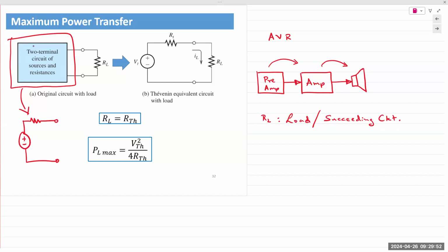Again, taking that example one step further, if you look at the speaker specs for any speaker, tiny drivers, headphones, earphones, big tall boxes, the speaker will always have a specification of impedance or resistance, if you will. And that will state it's either 4 ohms or 6 ohms or 8 ohms. Most of the big ones are 8 ohms. Headphones, at least the older drivers, used to be 32 ohms. Those are used to match the output of the amplifier. Most amplifier outputs are 8 ohms.